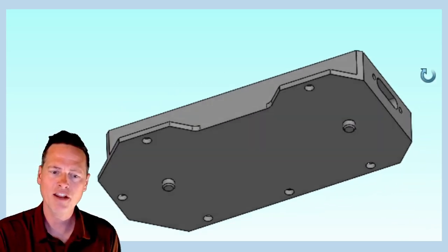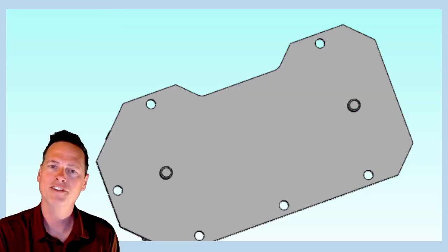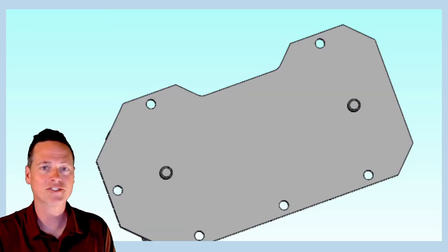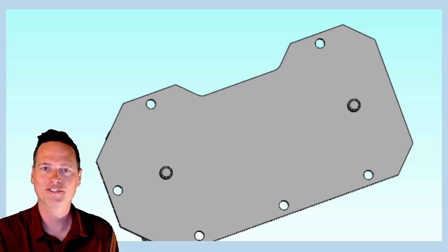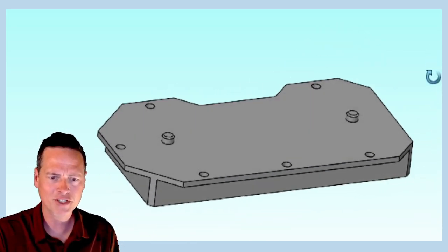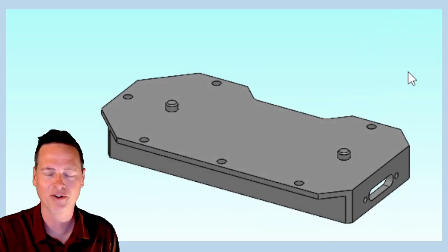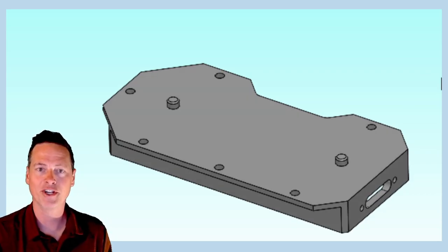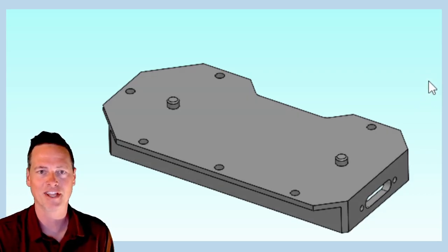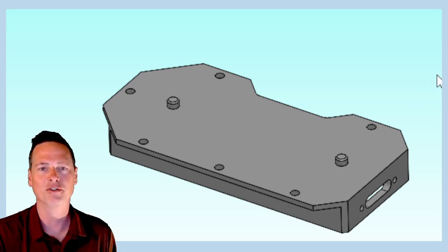but I'll go a step further. The datum A feature is a good primary datum feature, but it is a poor secondary datum feature for the same reason it's a good primary datum feature. It's so big. And the datum B feature pattern is a good secondary datum feature, maybe even pushing the limits as a 3 degree of freedom secondary datum feature, but it is a poor tertiary datum feature because it's so complex. You can get away with a 3 degree of freedom secondary datum feature in this circumstance, but for tertiary, it's just too much. So maybe one thing to say is, don't try to force these features to become something that they're not. These datum references aren't alphabet soup.